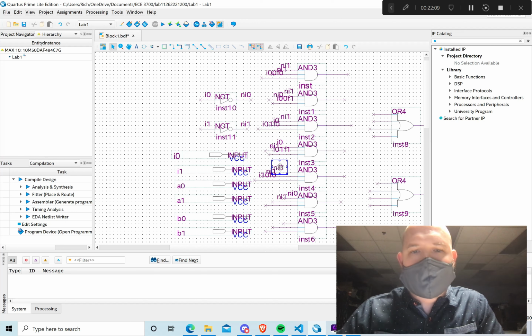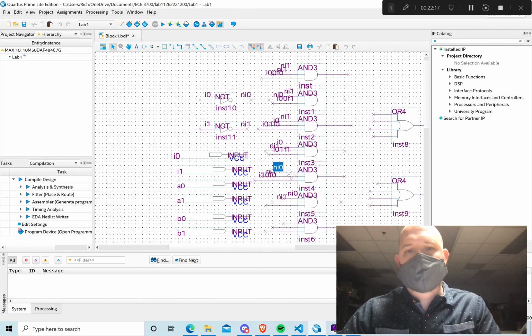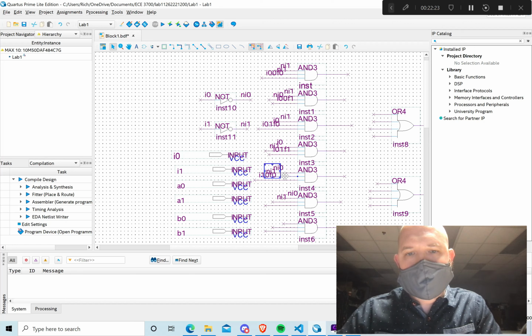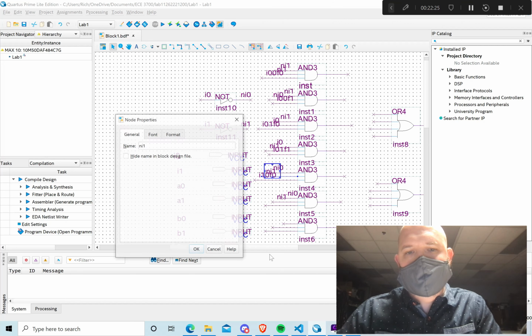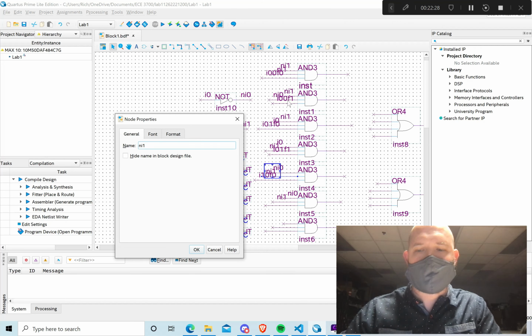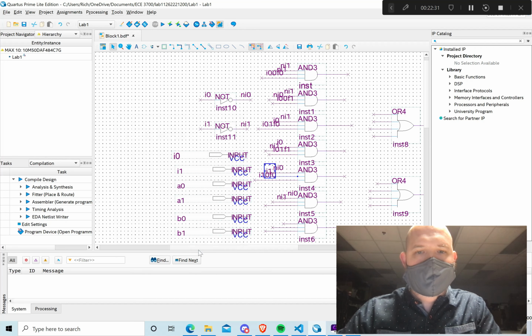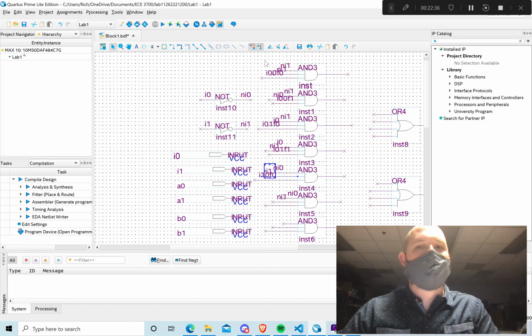Okay. I got a little bit off. So this needs to be an I0, which is correct. But then this one needs to be just regular I1, not negated. Otherwise, the two AND gates will drive 0, 0 as the selection, and we'll get errors. Everything needs its own unique combination of I's in order for a multiplexer to work.